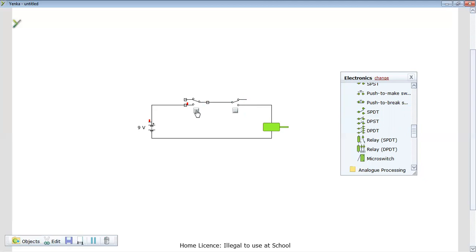because all that's going to happen is if I have the other one unselected, like with the light switch on the previous one, the OR circuit, I could happily press one of them and it would keep working. However, pressing one of them is no good here. I've only activated one of my valves. I needed both valves activated together to activate my cylinder here. So this is a simple example of the opposite or the inverse, which is an AND logic gate.